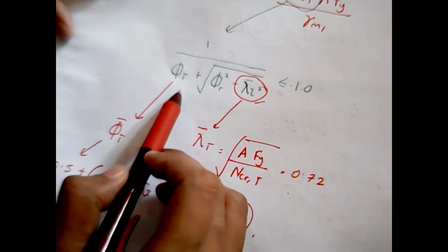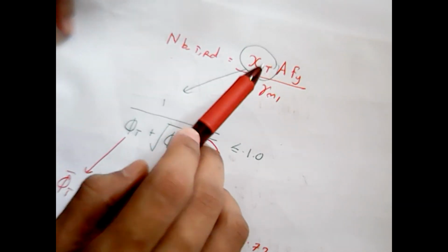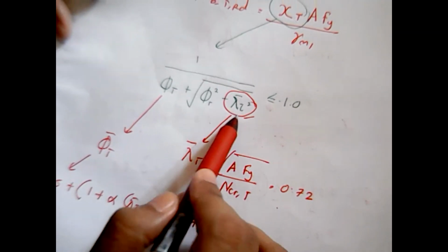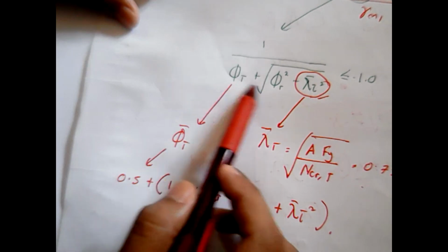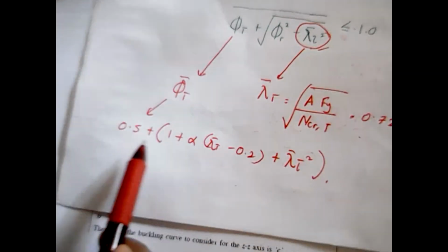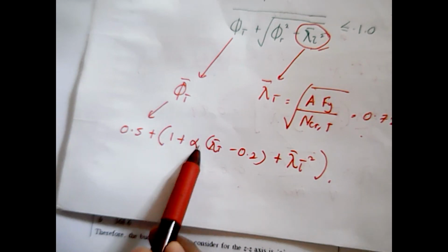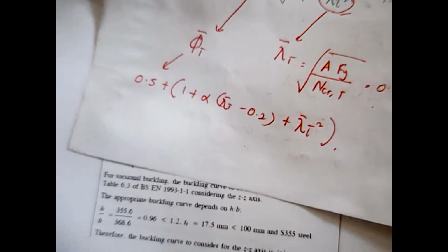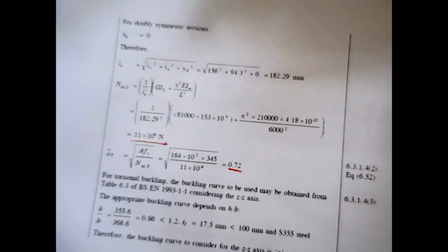So then you can find this equation for you to get the torsional buckling resistance reduction factor. Substitute it into these equations, but unfortunately we're still not able to calculate this. Therefore you need to find your alpha, which is the imperfection factor. The imperfection factor depends on the buckling curve and the cross-sectional resistance of your structure.